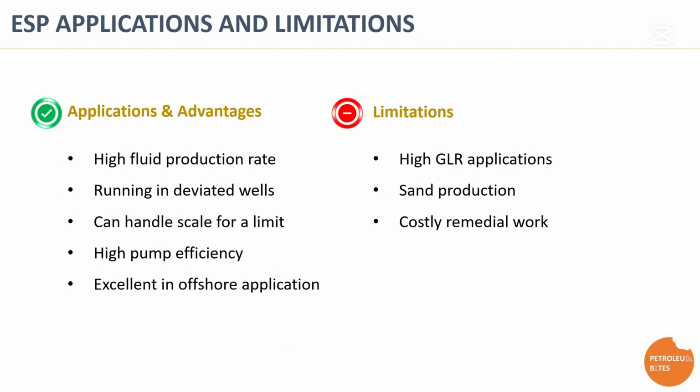When an ESP requires maintenance or replacement, retrieval and reinstallation necessitate a workover rig, which can be a costly and time-consuming operation, particularly in offshore environments. Additionally, ESPs are best suited for medium to high production rates and may underperform in low production wells, where insufficient flow can lead to overheating, inefficient operation, and equipment failure.